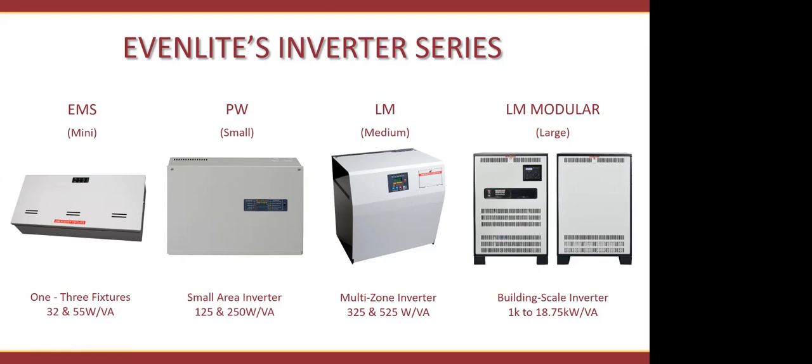So one, on all of our inverters, you do not have to account for that inrush. And here's why you don't have to. Our ratings on our inverters are a minimum of 4x crest factor. So what does that mean? That means that in a 250 watt inverter, it can withstand a 1000 watt inrush. So really, when we're talking about inrush, I highly doubt that if you had 250 watts connected to it, the inrush would get anywhere close to 1000 watts. So really, we have accounted for that.